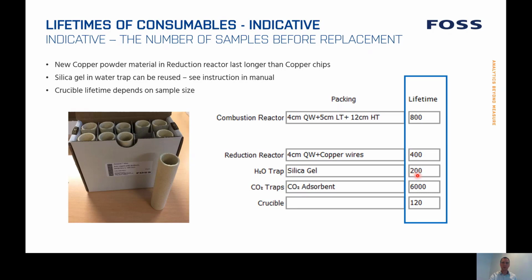You can visually see the silica gel: if it's pale, then it doesn't work. And you can also see it in the plots and the integration that the water is popping up. Then you need to regenerate this silica gel.